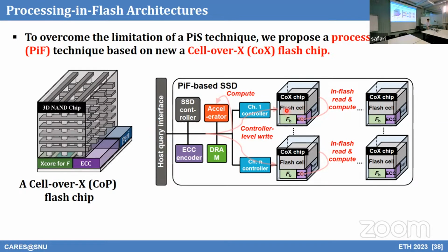Here, it's not possible because now you cannot recover bit errors without using this. So the key challenge is how we can reliably read inside the flash chip without putting a very heavy ECC decoder here. That was actually our key challenge in designing this.